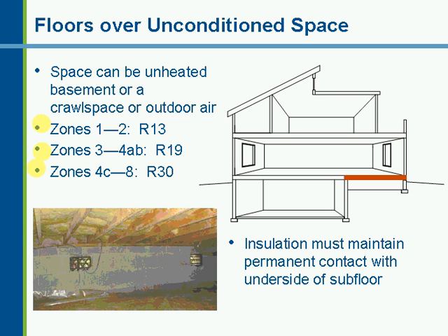There is a requirement that the insulation, when it is installed in the floor, be held firmly up against the subfloor at the top. So you can't let it hang down to the bottom of the members. You don't want an airspace above it, and that is part of the requirement in the code.